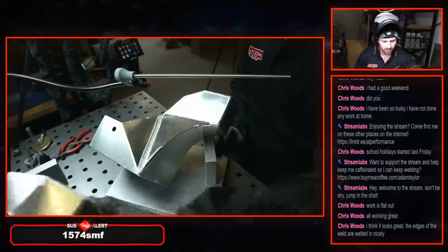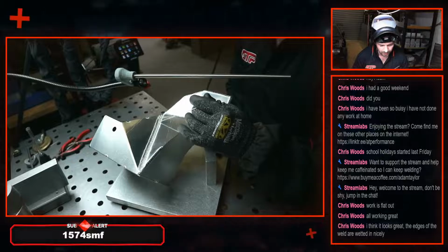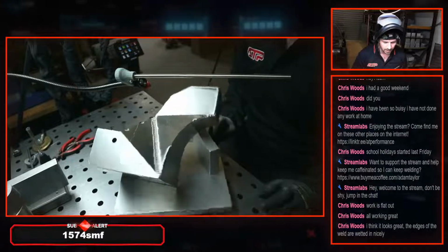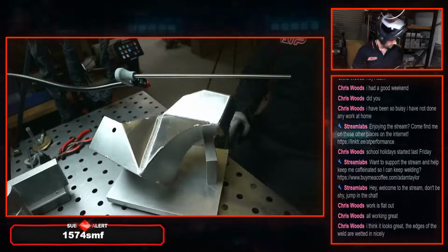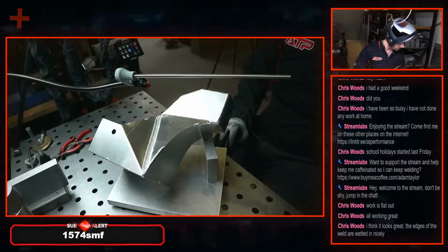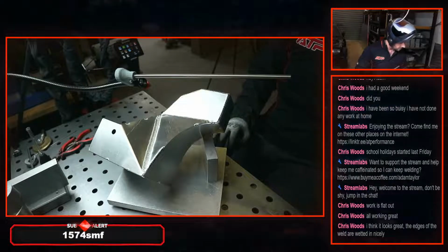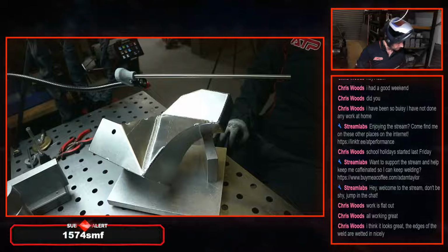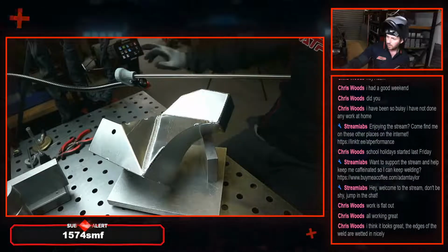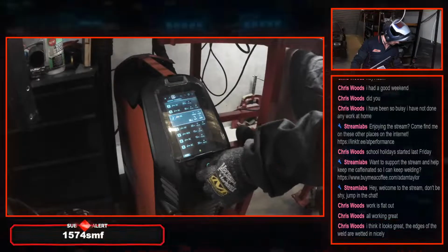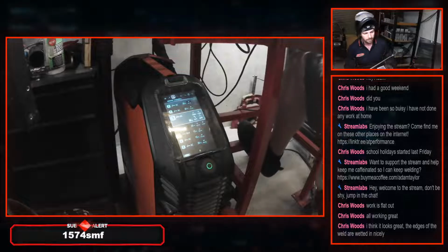Again, not too bad. I don't think we made a big difference by turning the frequency down. I think we might have got a little bit more consistency on those edges, which is really difficult for me to show you, especially in the dark. A little bit better on the edges, but as it got hot down the bottom there, we got a little bit of wicking in those dabs, so we won on one and lost on another. I think leaving it at 100 hertz, 110 hertz, probably good. I'll pop him back there just so we can save it, and I'll bring you guys over. So we'll just jump in there and save the changes, so we've got that for next time.